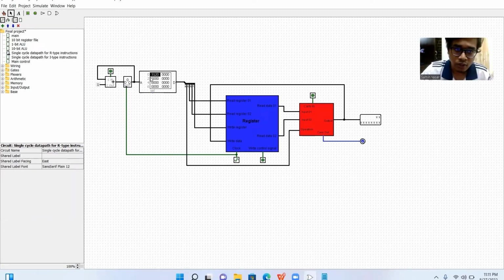operation. As we can see, the subtraction is 0, 2, 3, which is the fourth number, then register 1, then register 2, and register 0. Now the opcode, if 3 number or the 3 is this one, and the opcode is directly given to the ALU.